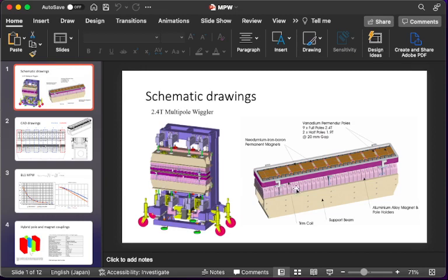The magnetic array is made of the magnet and the pole. The pole is the vanadium iron cobalt alloy to produce higher magnetic field than the magnet itself, because this soft material has higher permeability than the permanent magnet. The permanent magnet also can produce higher magnetic field from neodymium iron boron magnet.